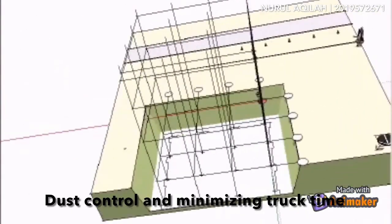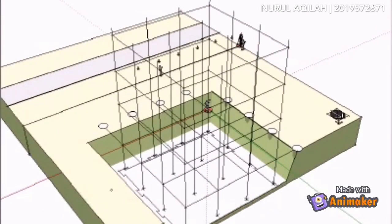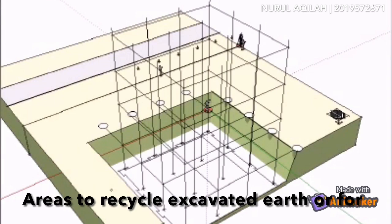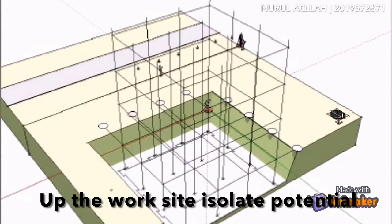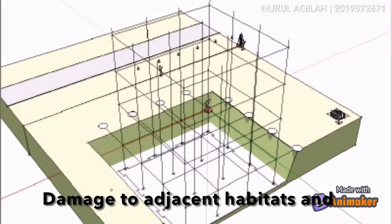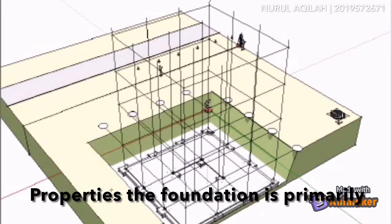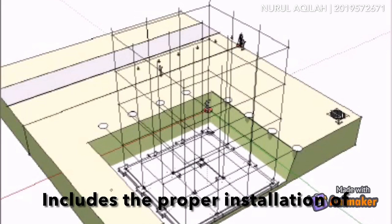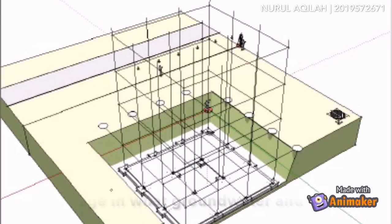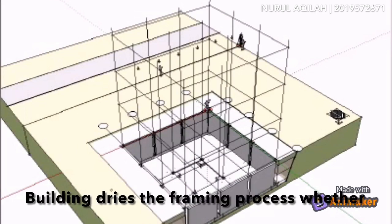Excavation means dust control and minimizing truck time for debris removal, setting up stockpile areas to recycle excavated earth for backfill, grading, and topsoil. In setting up the work site, isolate potential damage to adjacent habitats and properties. The foundation is primarily concerned with moisture control. This includes the proper installation of drainage, inward groundwater and vapor barriers, and other systems to keep the building dry.